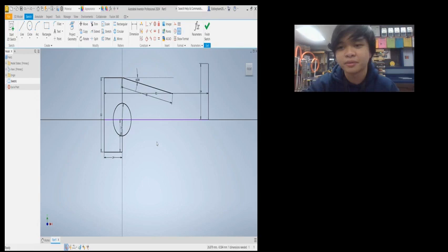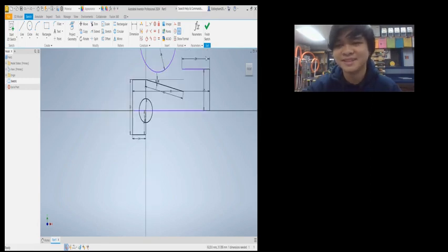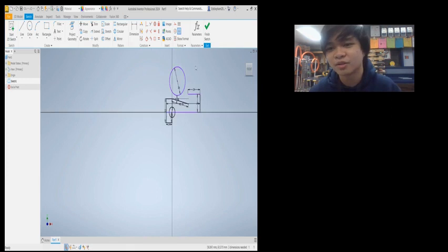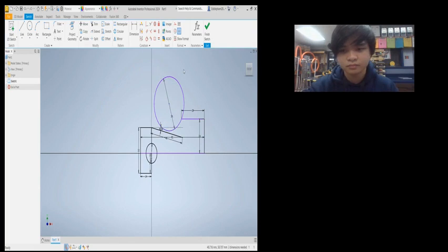And we're gonna go up, and then we're gonna draw the top part so we can make the circle and constrain it. So it's 29, and then we create the radius 19 circle, which is 38 diameter. Then we constrain it using a coincidence constraint.